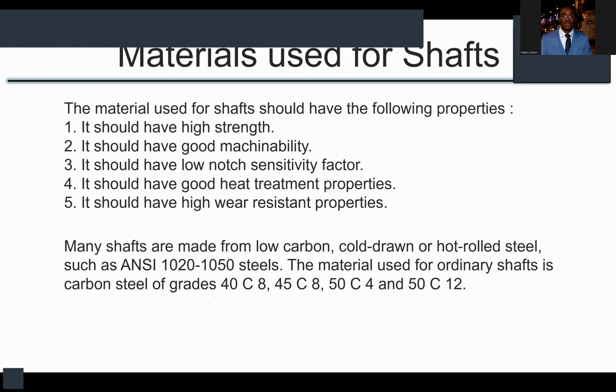Heat treatment increases strength, so this goes with high strength. If you heat treat your material, it increases strength, but it also helps the material withstand very high temperatures. Whenever your shaft is rotating, it will generate a lot of heat as a result of its motion, and particularly with the materials used. So heat treatment is needed to strengthen your shaft and to provide it with properties that let it carry a lot of heat and resist wear.